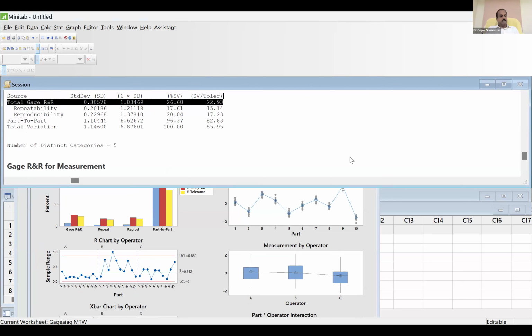But a measurement system is considered really good and capable if the gauge R&R value is less than 10%. All that you need to do is generate readings. This is a pilot reading. Please note, this is not the real data collection. Do you understand? What are we doing now? Pilot data collection. This is not the actual data collection. The pilot data collection of 90 readings we collected and we feed it in Minitab, and that will tell us whether the gauge R&R is okay or not. And what is okay? Less than 10% is okay. Clear, all of you?